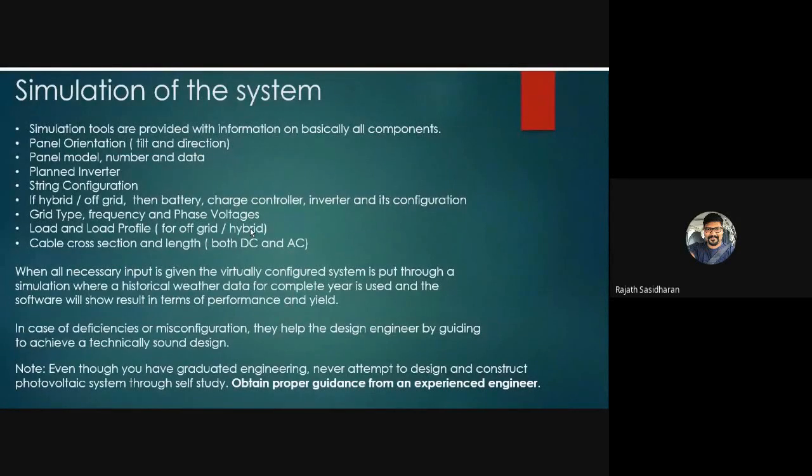The simulation of the system. The simulation tools are provided with information on basically all components associated with it. Maybe inverter, battery, charge controllers, solar panels, everything. Everything is input, right? These are all the factors that we feed into the simulation system. Then we also give them the panel orientation, the tilt, and direction, right?